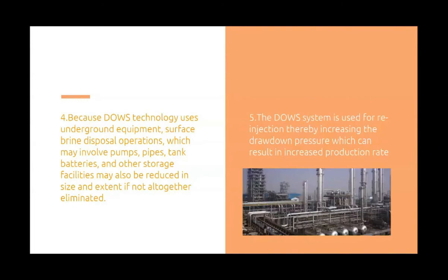Okay, for the fourth advantage of the downhole separator: because the downhole oil-water separator technology uses underground equipment, the surface brine disposal operation, which is the produced water disposal operation that may involve pumps, pipes, tank batteries, and other storage facilities, can also be reduced, hence minimizing the facility size and reducing the additional cost of facilities.